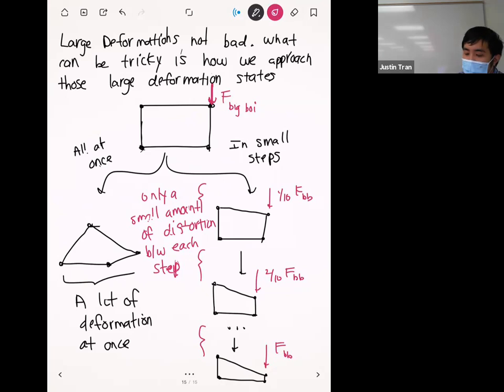Okay. But when you suddenly apply all the deformation at once, because the stiffness of the element depends on its geometry, it may not properly adjust to it. Just because you go from one configuration and then all of a sudden you're in a different configuration altogether. All right, and so this is typically how you deal with situations with large deformation, is that you apply the load incrementally like this. And so the large deformation that you get is reliable, and more so than before.